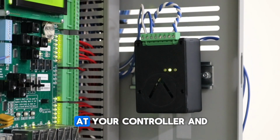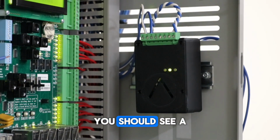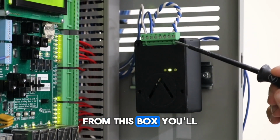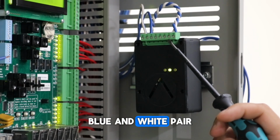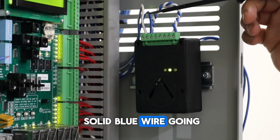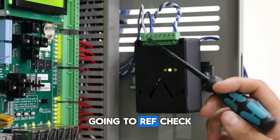Now we're going to go over how to connect to the DAD unit. First, take a look at your controller and the DAD unit. On the right side of the machine room board, you should see a black box. This is the DAD unit. From this box, you'll see 4 wires connected to it. One twisted blue and white pair going to the group network plus and minus, a solid blue wire going to 24 volts, and a white and blue wire going to ref.